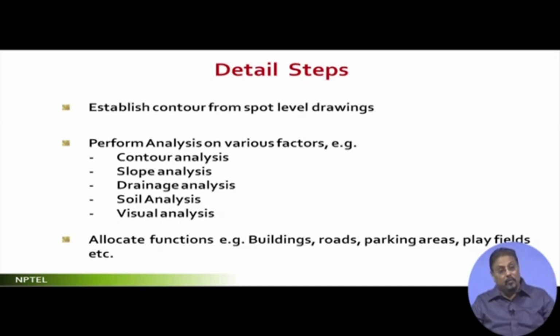Okay, rather survey time. You have instructed your surveyor on how to really find out the positions of different elevations. See, it is meaningless to go for very minutely measuring all the elevations. It's not necessary. If you find a flat land where a few corner or reference points' elevation will give you a good idea about the topography, that is good enough. But if you find in between there are some bit of changes, which I have explained in my earlier lectures, then you further subdivide and go for detailed elevation recording. So establishing a contour is the first step of the landform work.